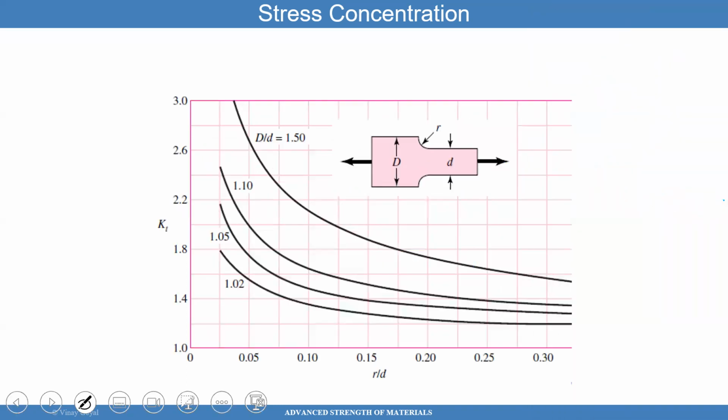More examples. You have a stress concentration where maybe the plate drops from a larger width to a smaller width. What do you do with that? Very similar process. You have a fillet there. You don't want a square corner there because then it will be easier for things to crack there, right? So we normally put a fillet in the design process. And so this tells you how to calculate the stress right at the fillet. Again, a very simple process.